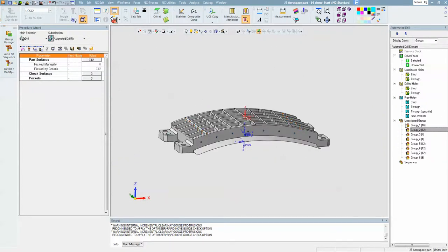Okay, so we're going to auto fit for all unassigned groups. And so it's going to go through my library and look for previously saved sequences, and it will attach them according to a geometric range. And this works really good with imported data.